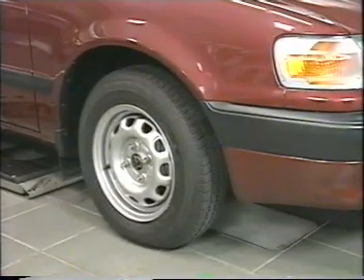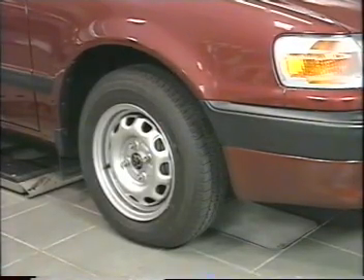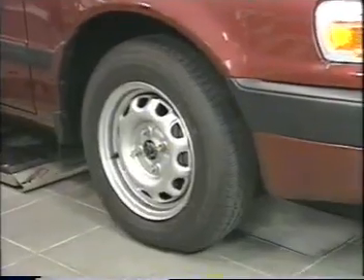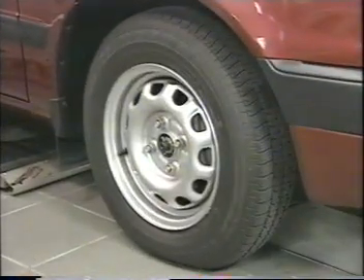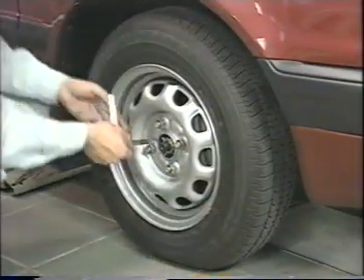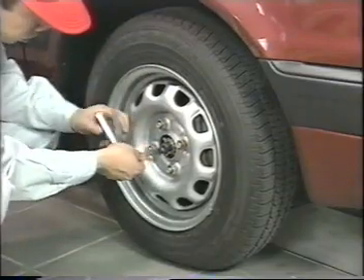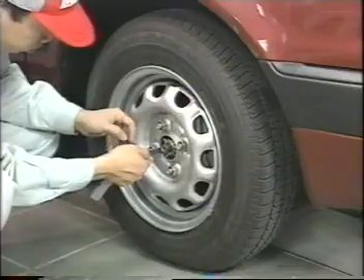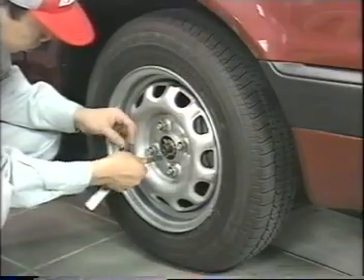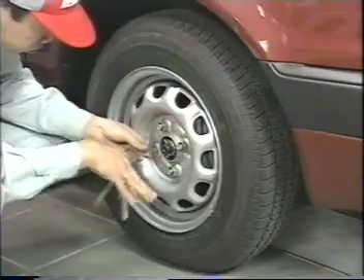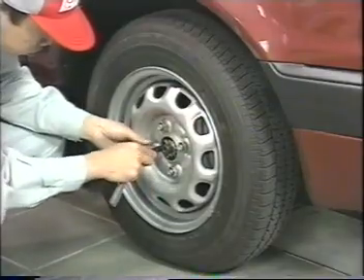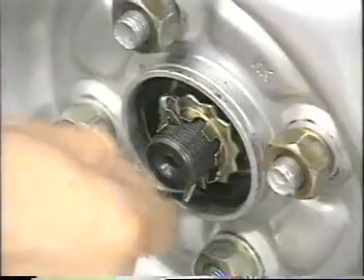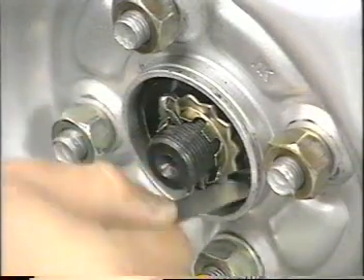Now let's see the inspection and maintenance when tires are causing vibration. First, check that the wheel center is aligned with the hub center. Using the thickness gauge, inspect the hub-to-wheel clearance along the entire circumference. If the clearance difference exceeds 0.1 millimeters, adjust the position of the tire and refit it at the position with the least difference.